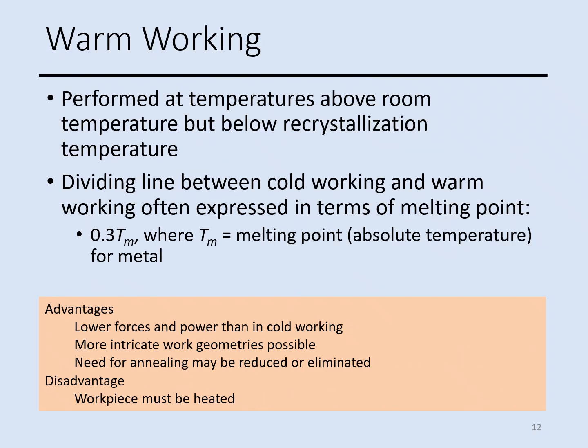The next metal forming process, considering the temperature, is called the warm working process, which is performed at temperatures above room temperature, but below the recrystallization temperature, where new grains can be formed. And this temperature is a function of melting point.